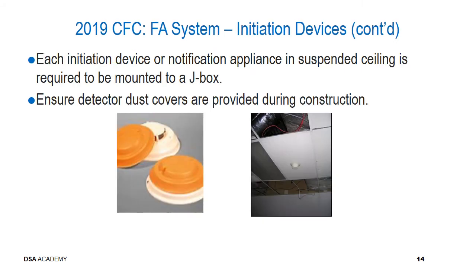Each initiation device or notification appliance in suspended ceilings is required to be mounted to an appropriate J-box. Ensure that detector dust covers are provided during construction, and most importantly, that they are removed upon completion of construction.